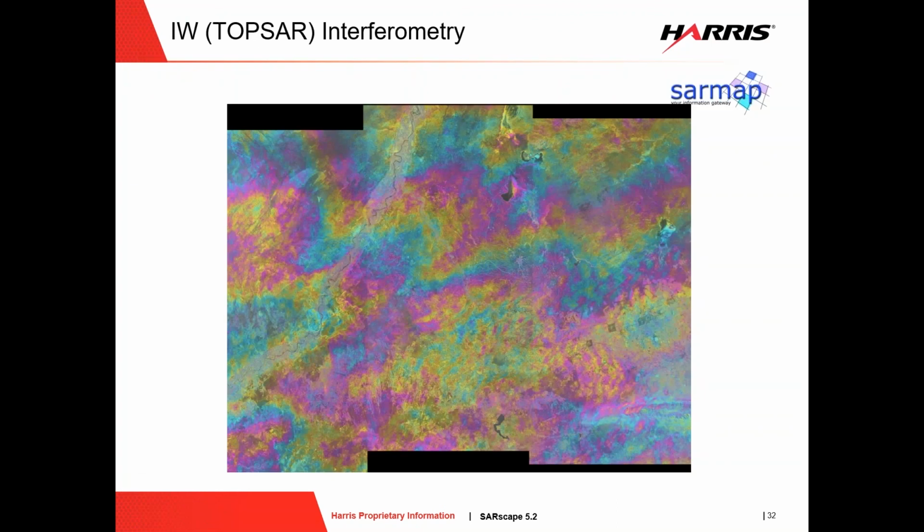Okay, nice. What about the phase? In this case, we see an interferogram still in slant range geometry of one interferometric wide swath, so that means of one TOPSAR acquisition obtained from Sentinel-1. We see 1, 2, 3 subswaths. We start to be used to subswaths with Sentinel, and we see nice colors everywhere.